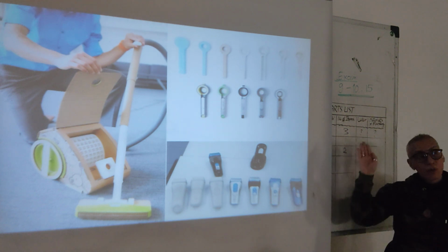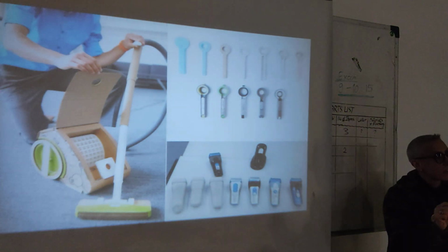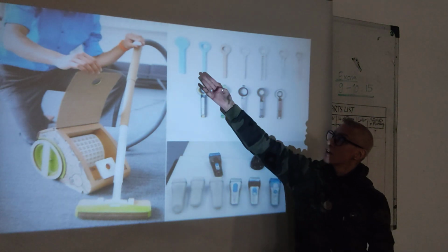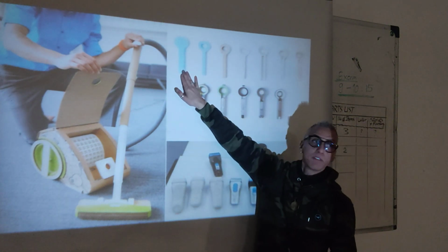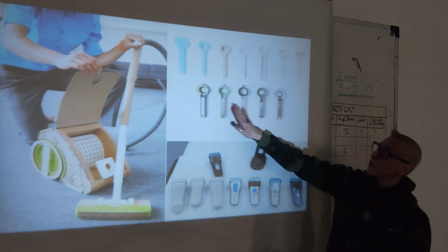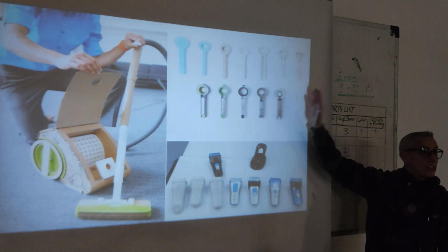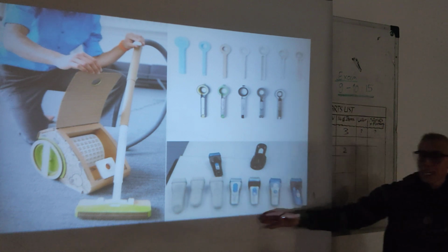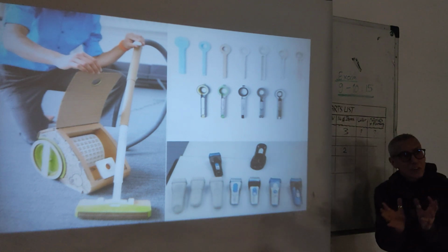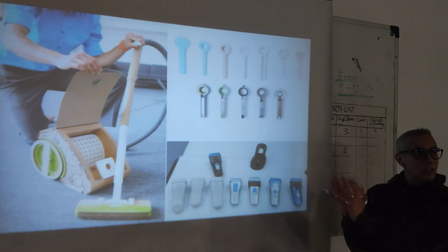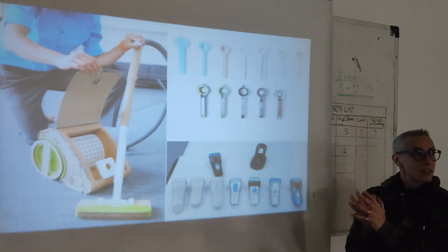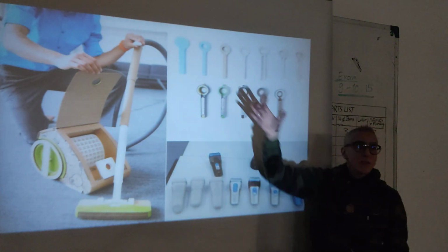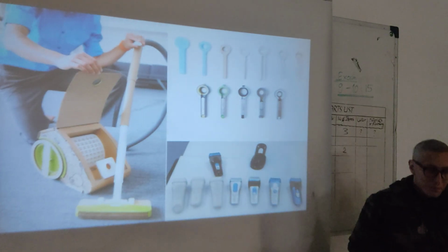Now, presentational models can be made so detailed that they look like a totally real product. So it can be made out of, for example, foam, developed until it reaches the final shape, or out of clay. The starting material can be something, and the end result can look extremely realistic. Or left simple, if it's just for shape testing.